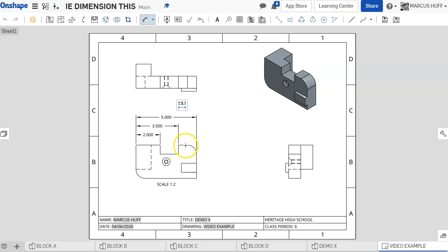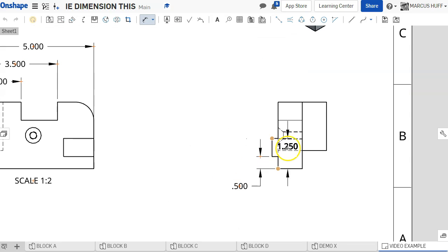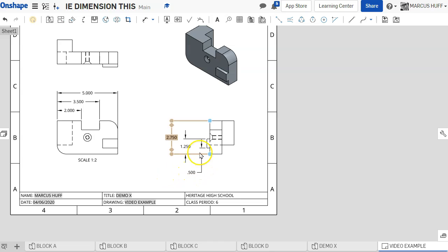On this side we would go from here to here across the bottom, get that centered. And as I'm looking at this, I like this side better, so I'm going to undo that, and we're going to show the height information on this side. Alright, notice how I move these around so it's easy to tell where the measurements are, that there's no overlap and that sort of thing. And I will need to add one more from this edge to here. Again, notice how all of these measurements are referenced from this bottom edge.